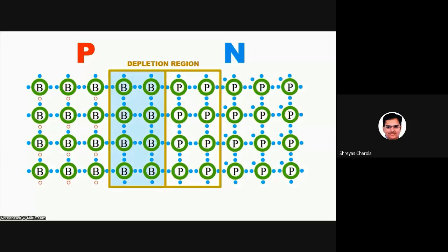On the other side, a layer of n-type silicon just had its electrons leave. Remember, this also used to be neutrally charged. Now the lack of electrons makes this area have a positive charge. The layer of atoms at the border is now ionized and is depleted of charge carriers. This prevents any current from flowing. You can see why the PN junction is useful when we attach it to a circuit.